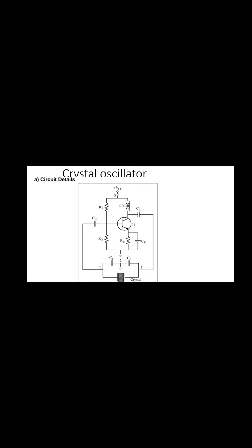The crystal oscillator: we have to discuss that crystal materials, namely Rochelle salt, quartz, and tourmaline, exhibit the piezoelectric effect. If an AC voltage signal is applied across the plate, the crystal will start vibrating at the frequency of the applied voltage and produce an AC voltage. Such crystals which exhibit the piezoelectric effect are called piezoelectric crystals or quartz. Quartz is the most commonly used crystal because it is inexpensive and readily available in nature.